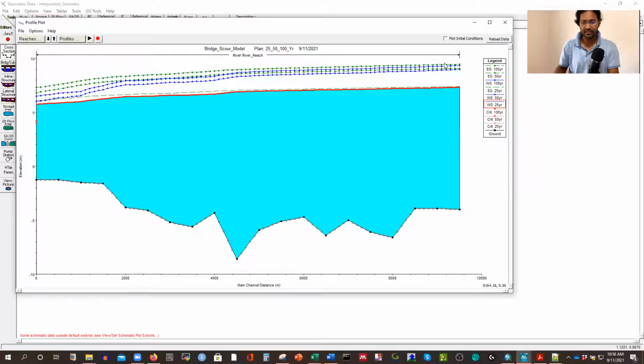So from that level, when the flood level will be 100 here, that means your water surface level will be here, and from this level you have to fix your bridge clearance, the bottom of the bridge, right? We will have that calculation based on the navigation route. So from the 100 year return period of flood level, you have to fix the bottom chord of your bridge. Then even for a 100 year flood, definitely the size of the ship, if it is allowed for class 1 navigation route, or whatever the number of the navigation route, definitely it will pass. So that is the engineering decision you have to make.